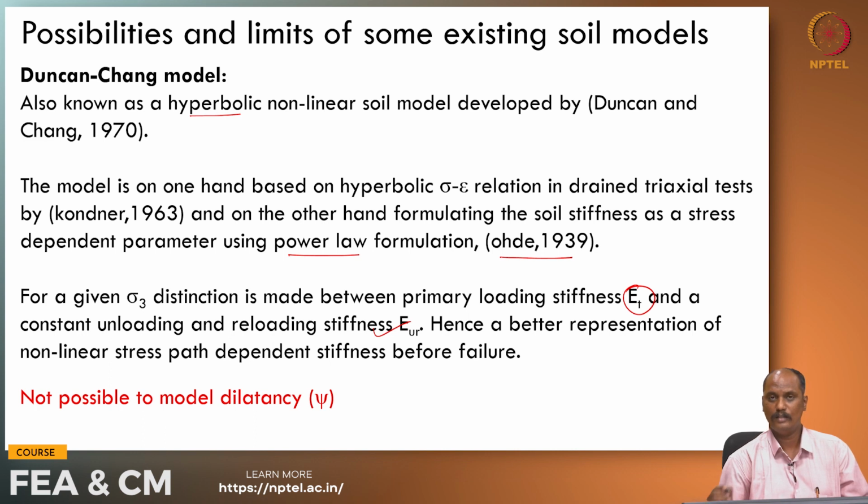If you remember, in the previous models we did not have this unloading reloading stiffness, but here we have this unloading reloading stiffness Eur, hence a better representation of nonlinear stress path dependent stiffness before failure. All that we are trying to do is to see how far the real soil behavior, or the real situation prevailing in the field, can be captured with these stress strain relationships or constitutive models. And the limitation is that it is not helpful to model the dilatancy parameter, namely psi.